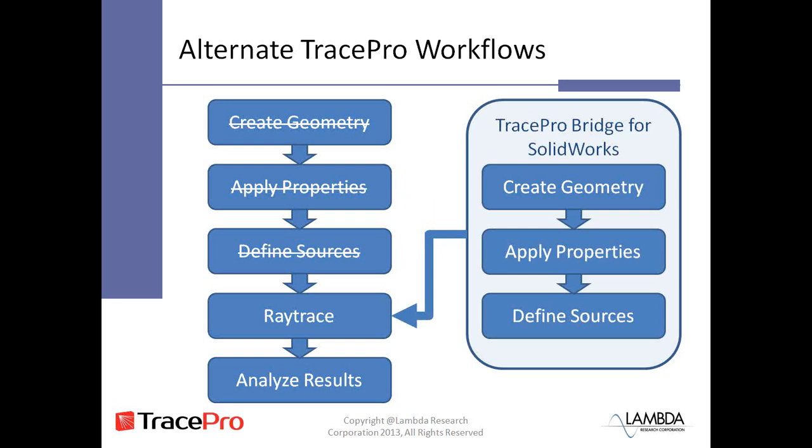If you're a SolidWorks user, we also have the TracePro Bridge for SolidWorks option. Once again you're creating your geometry in SolidWorks, but now the TracePro Bridge allows you to apply all the optical properties and define your sources in the SolidWorks environment. These are saved as part of that SolidWorks model. From SolidWorks, you then export a TracePro file for analysis, where you run the ray trace and analyze the results in TracePro itself.